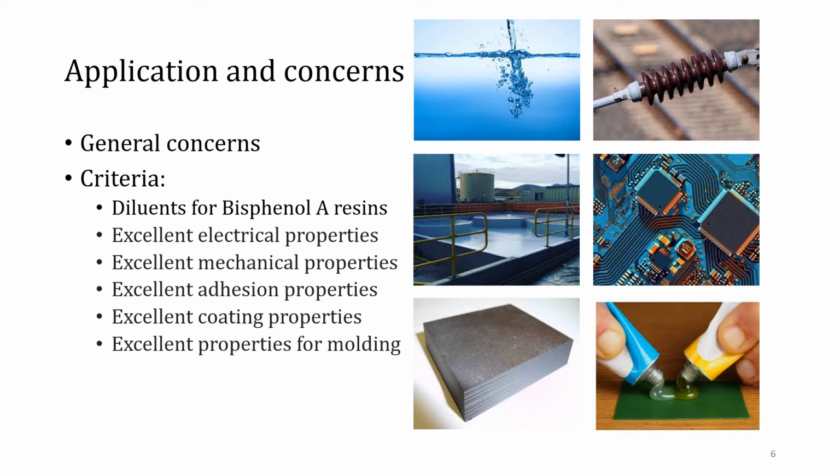Used in glass fiber reinforced plastics and filament winding, cycloaliphatic epoxy resins not only overcome the disadvantage of bisphenol A type epoxy resins with low heat distortion temperature, but also, because of the low viscosity of the system, the operation is more convenient.